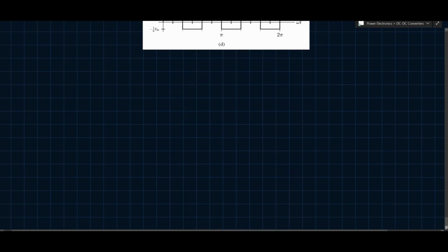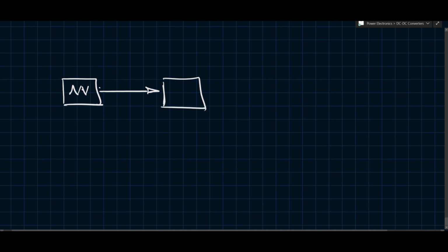So now the last thing we can discuss is generating a PWM for something like this, right? There are a couple of ways you can do it, but the best way is probably to have a single carrier. So you'd have a single carrier. This is your carrier, and you would compare it. Let's give it a comparator. Let's just draw it as a block like this, so that we don't have to get into too many details. So that's your comparator block.